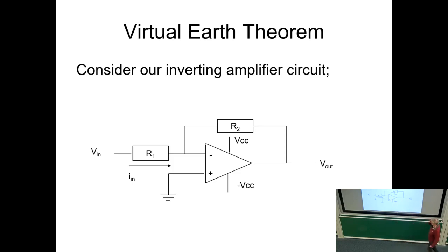And as I think I mentioned at the end of the last lecture, what that means is that the op-amp is actually adjusting its output to maintain the difference of these two points as being 0. If the input voltage changes, and so this voltage looks like it's going to change, this will adjust its output to rebalance everything so it's 0. So it's balancing everything at the 0 point, or balancing it to this point, which in this case happens to be 0. So that's all the op-amp can do. Adjust its output, one way or the other, to maintain 0 at that point. And that's negative feedback. It's adapting itself to maintain this 0.